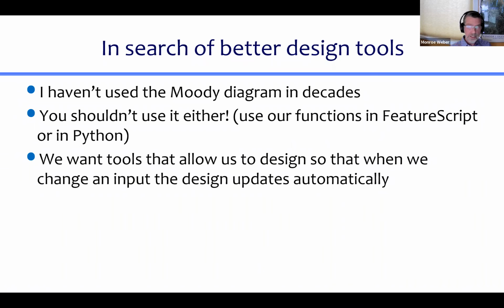We want tools that allow us to design so that when we change an input, the design updates automatically. So do you see this problem? If you use the Moody diagram as a step in your design process, it means that when the client comes back and says, you know what, that flow that we were designing for, we've done another piece of our study and we realize that we need to increase the flow by 20% to meet future demand, and if you use the Moody diagram to design your system, you have to go back and do the Moody diagram all over again for all the pipes in your system.